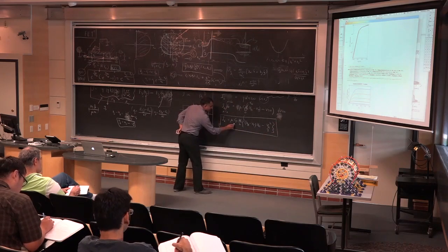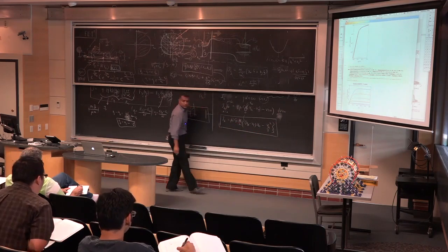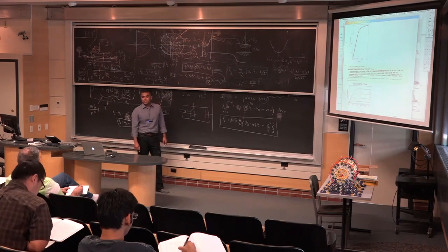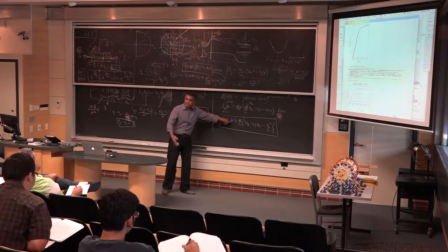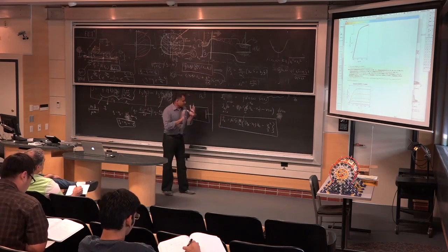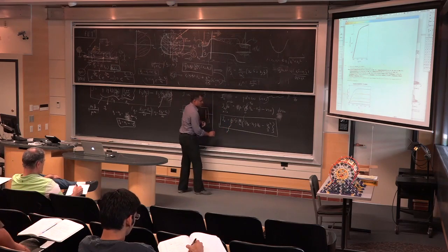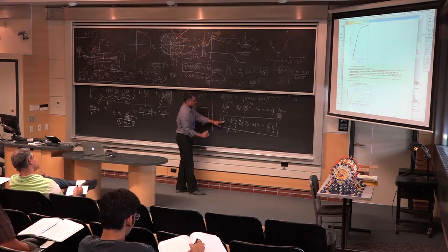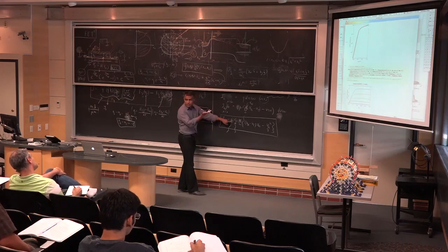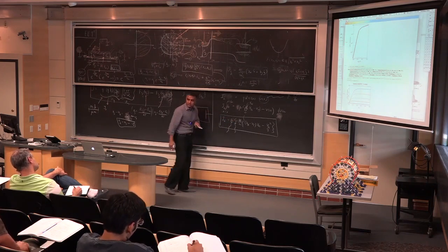And what appears here, which does not appear in the ballistic transistor, is L and mu. These things don't appear in the ballistic transistor. L is the channel length, and mobility depends on scattering and all that stuff. Classically, FET physics has always focused on this picture, and the idea was always to improve the current, to make a transistor better and better. To do that, you look for high mobility materials. You look for high gate capacitance, so you make the insulator thinner and thinner, and use high Ks and that sort of thing.